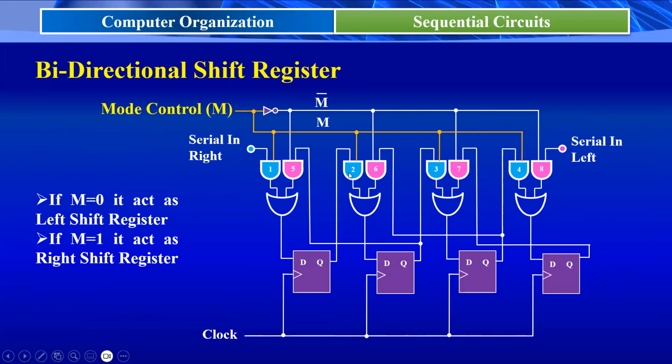Again, here I am using a control logic circuit. Similar to the previous two cases, that is the parallel and serial shift registers, we use this type of structure, as well as in the controlled buffer register case. Only the control signal changes, and here these inputs change. If it is a shift right, here data bits are moving from this end to this end. For that case, I use gate 1, gate 2, gate 3, gate 4.